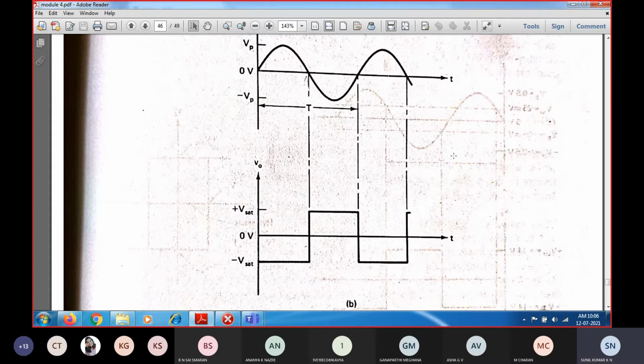Whereas when you employ the positive feedback configuration of the op amp, the output is given to the non-inverting terminal. In the inverting configuration, the output of the op amp is given through the feedback network to the inverting terminal. So we can say that the op amp is configured in negative feedback configuration. In negative feedback, we have seen the inverting, non-inverting as well as voltage follower configurations.